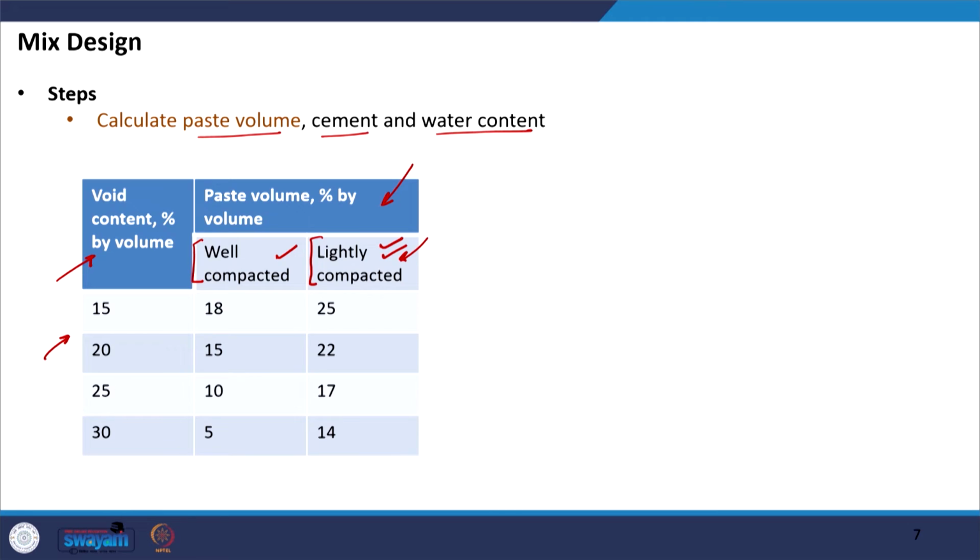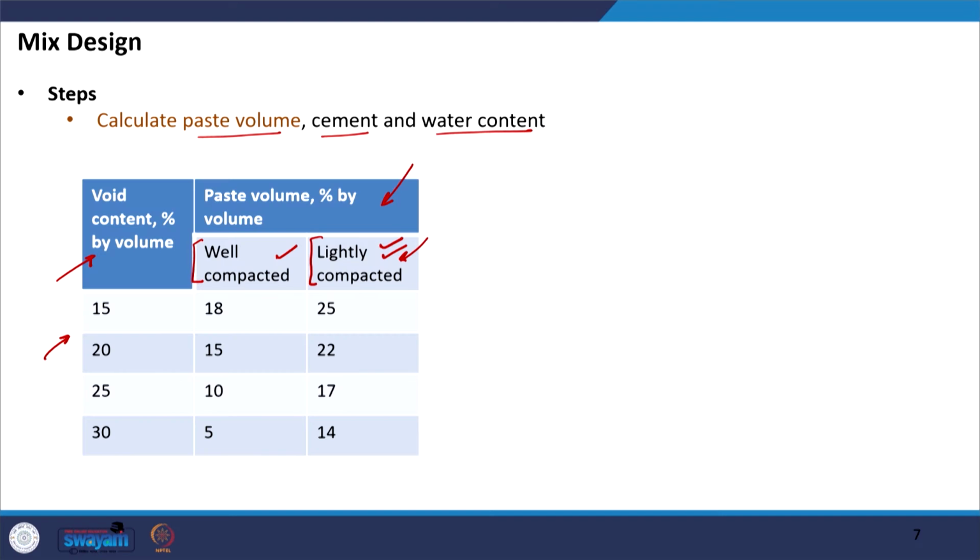One of the again shortcomings in the present form is that the code does not say how to produce the mixtures in the lab. Should it be produced in the similar way we are producing the concrete mixture? The answer is no. Then how to produce these mixtures in the lab, because we have seen in the last class that a conventional concrete mixture is filled using a vibrator, even the same we do in case of DLC mixtures.